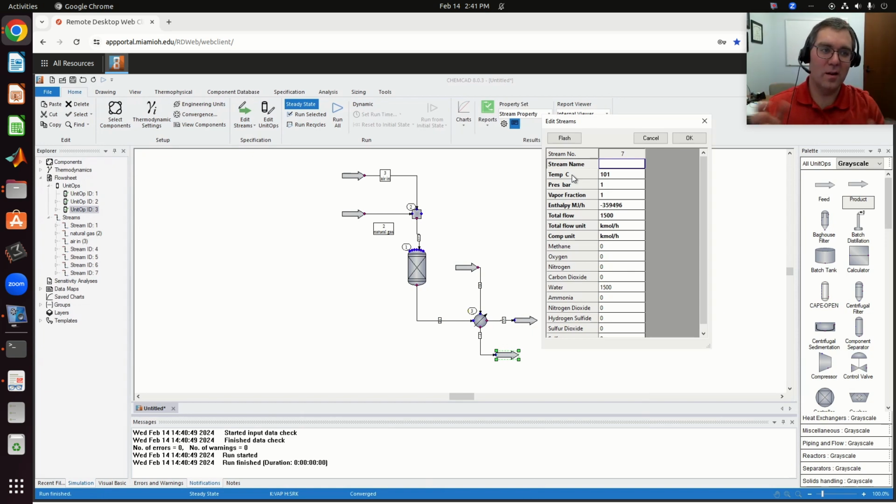But again, remember in our project, in case you're watching this from elsewhere, we're using natural gas to strip ammonia from water. The water contains ammonia, it's sour water, containing a little H2S. We're going to use natural gas as our stripping gas. So coming out the top, we're going to have natural gas plus some ammonia plus some H2S, which we're then going to send to a flare. So we're just modeling that flare process.